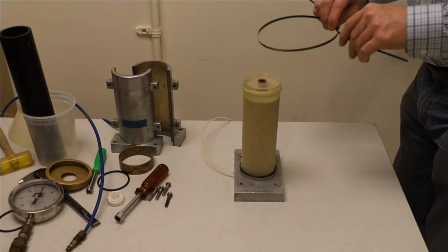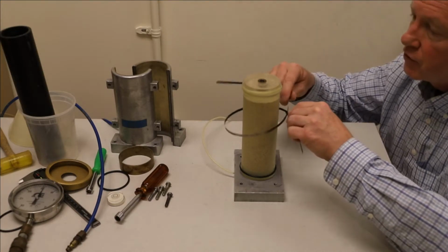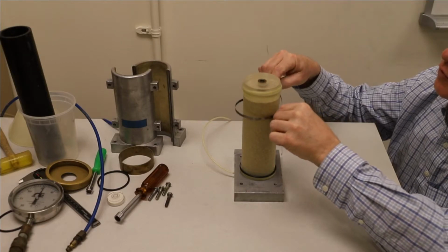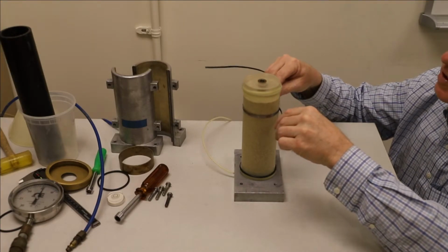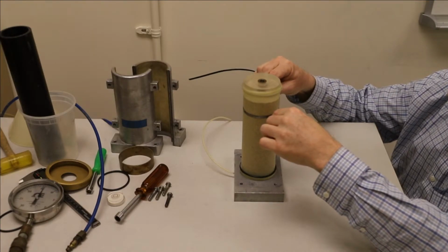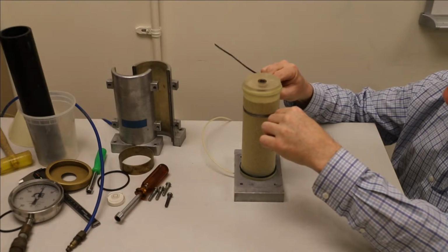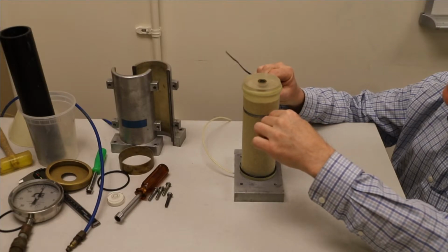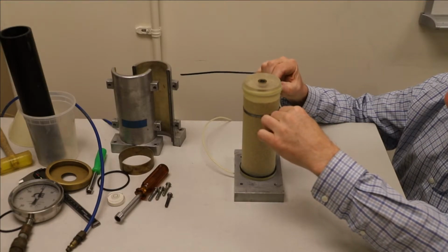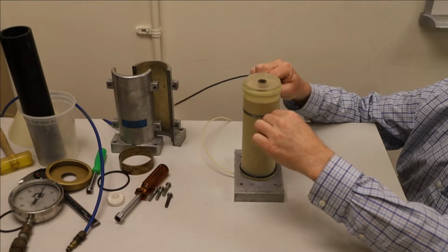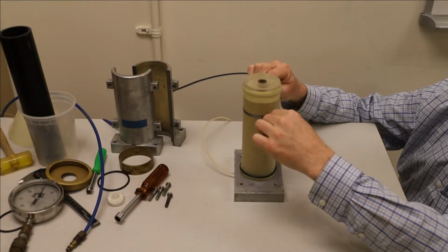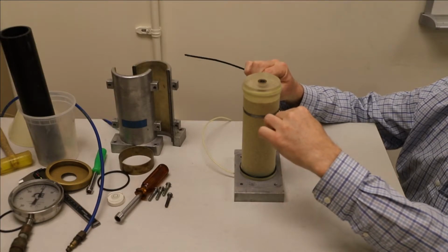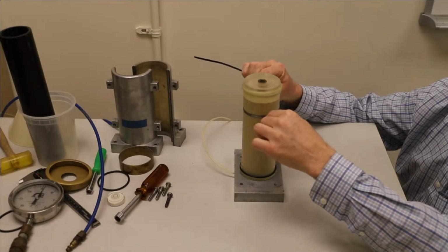So when you wrap it around something that's roughly cylindrical, you can read the equivalent diameter of whatever you're wrapped around if it was a circle, right? It's basically measuring the perimeter and dividing by pi. And I can measure that to the nearest thousandth of an inch with this because it has a vernier scale.